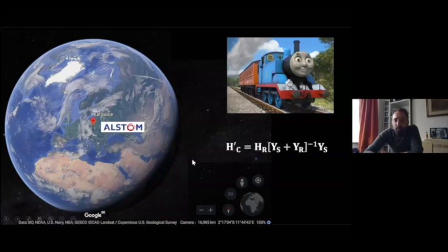What we have measured already is YS. So we got YS from measurements in Italy. So we're going to Poland now, to Katowice, where the train lives, to measure the vibroacoustic frequency response function of the train without the compressor and the mobility of the train without the compressor. We can combine those then to determine what is the relationship for the coupled structure where force is applied to the junction between the 2 and the sound pressure is measured inside the train.